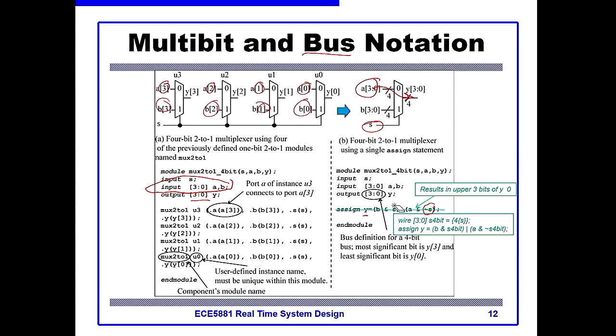Unfortunately, the textbook made a bit of a mistake here, which is a little bit bad, but we can fix it pretty easily. So what happens when you AND A, we'll do the B one. If you AND B with S, when S is 1 bit and B is 4 bits, what does Verilog do? Well, unfortunately, it will generate a 1-bit result.